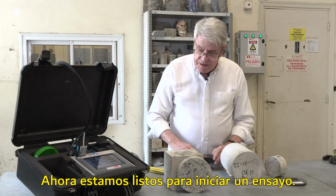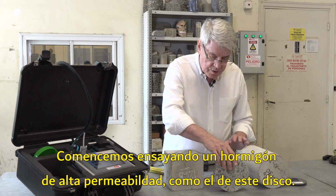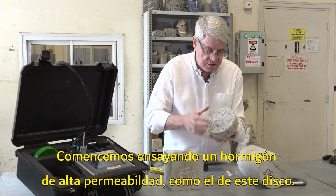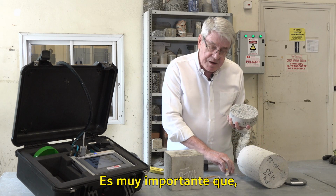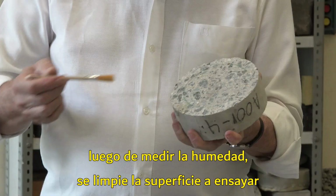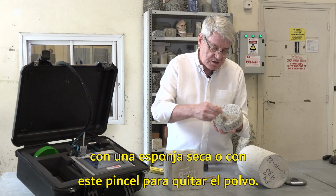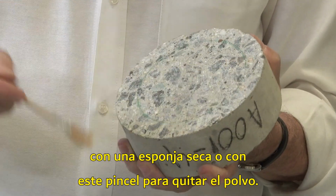So now we are ready to start a test. Let's start testing a concrete with a high permeability, which is this disc. Very important is that after measuring the moisture, the surface has to be cleaned with a dry sponge or this brush to remove dust.